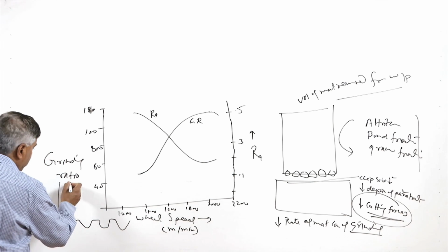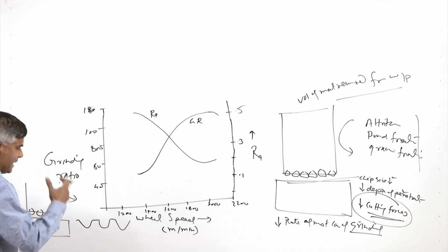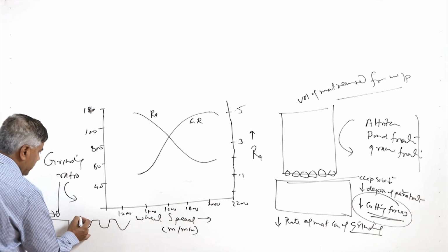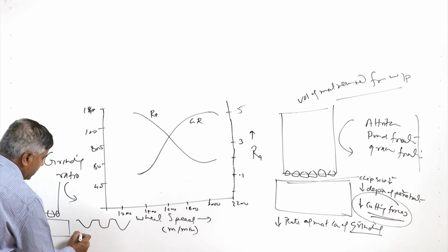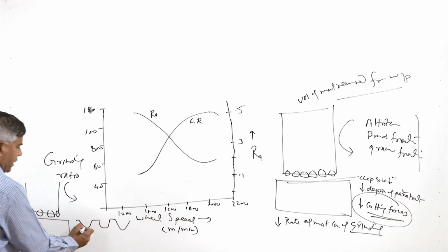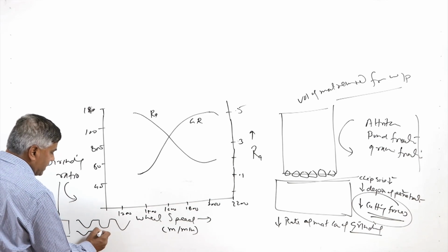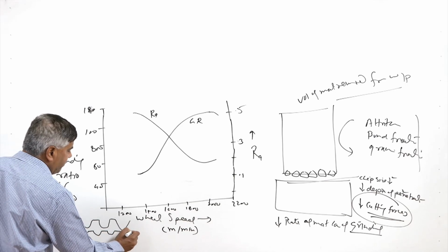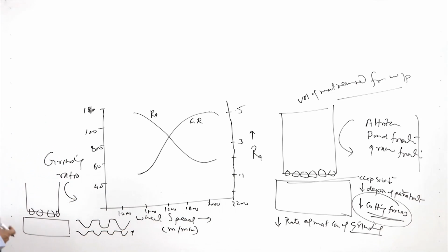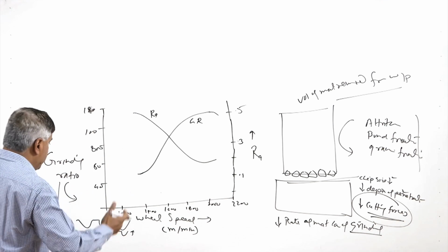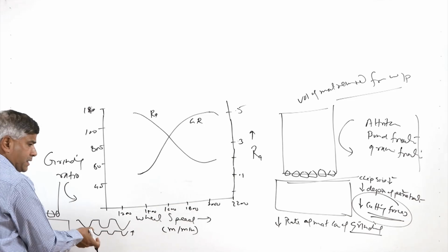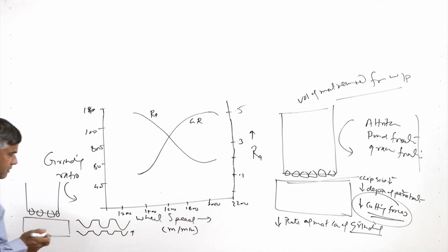On the other hand, when the wheel speed is increased, the depth of penetration gets reduced. So, under identical conditions, the depth by which the abrasives are able to penetrate into the workpiece gets reduced, which in turn leads to higher removal of material due to the increased speed, and at the same time reduced depth of the scratches and grooves formed on the surface of the workpiece.